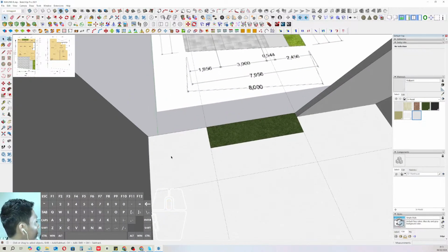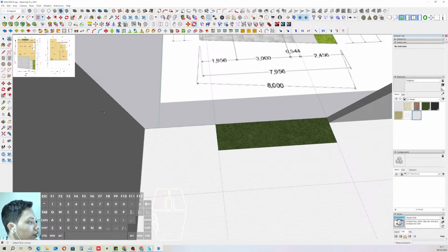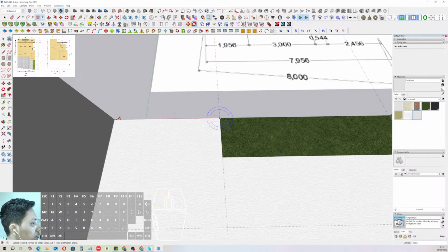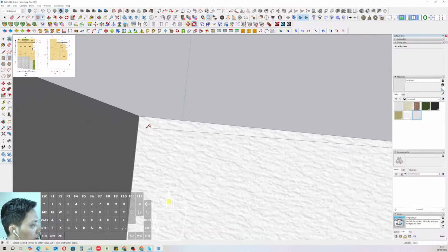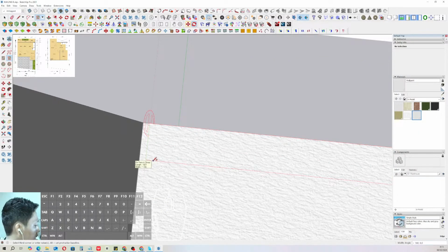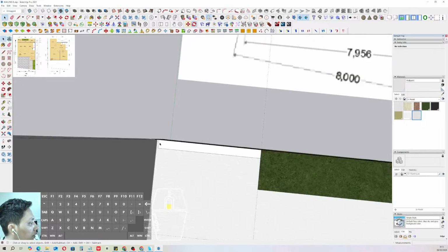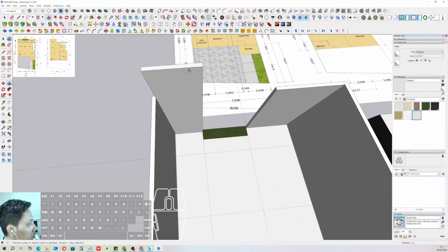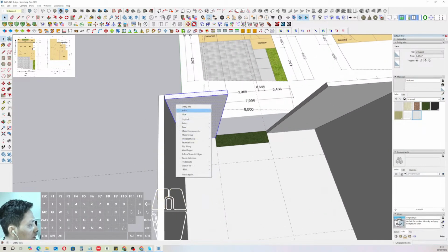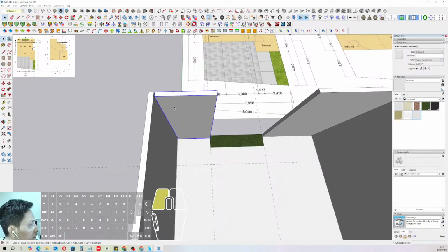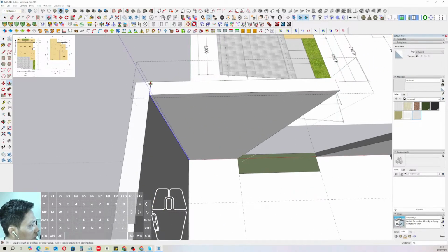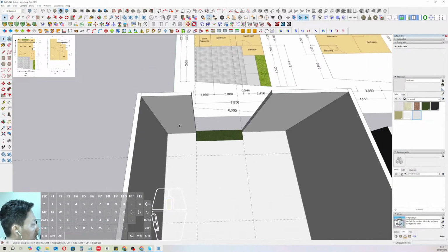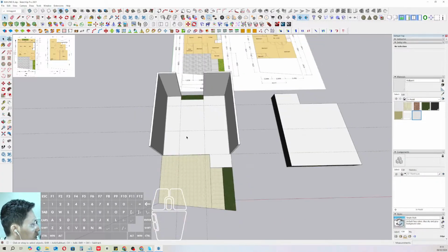Okay, and after that, we can select the rotate rectangle again and click from this position to this position first. We type 150 millimeter for the standard wall thickness, use the push pull, make group, and set the wall paint. Then we can set the connection of this wall.